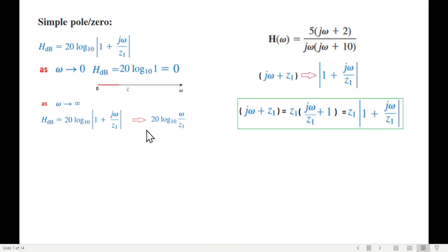As we had seen, this will be a 20 dB positive slope. So we plot it like here. Now this was our corner frequency, so it is moving away, almost towards the higher end side, or infinity as we call it. Now we have these 2 points, so we can combine them. Up to the corner we keep the 0 line, and from there we take this slope. So this will be our amplitude plot for a simple zero factor.